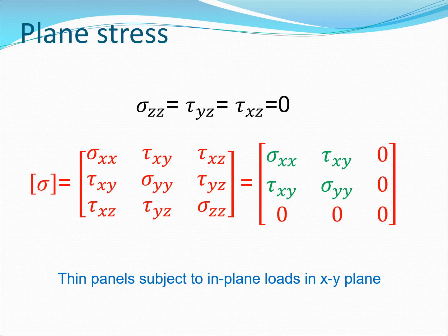Of course, in the old days when all the calculations were made by hand, this kind of reasoning was more important. But today you have access to computers, and so it may not be so necessary to make these approximations. So always remember, before you make any approximation about plane stress and plane strain, to check whether it is justifiable for the given structure or not.